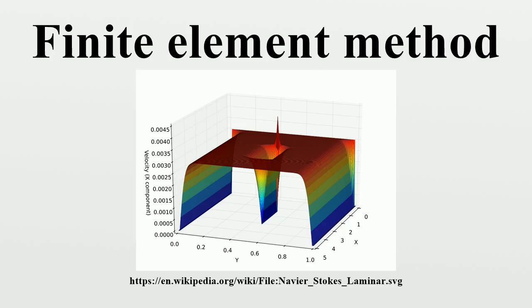While the divided small elements of the complex problem represent different areas in the physical system, FEA is a good choice for analyzing problems over complicated domains, when the domain changes, when the desired precision varies over the entire domain, or when the solution lacks smoothness. For instance, in a frontal crash simulation it is possible to increase prediction accuracy in important areas like the front of the car and reduce it in its rear. Another example would be in numerical weather prediction, where it is more important to have accurate predictions over developing highly nonlinear phenomena rather than relatively calm areas.